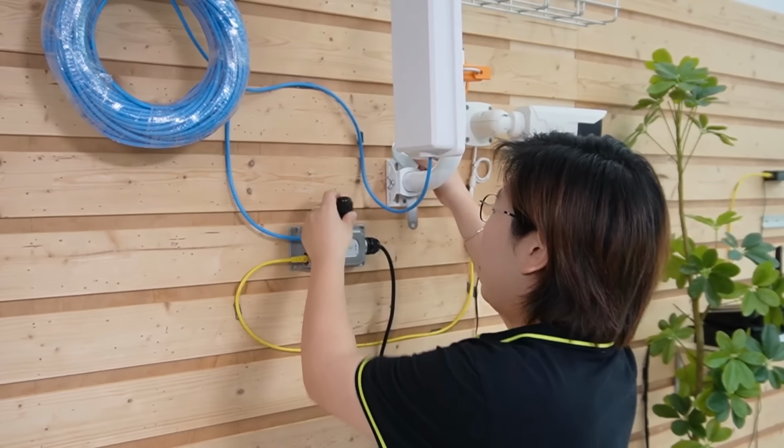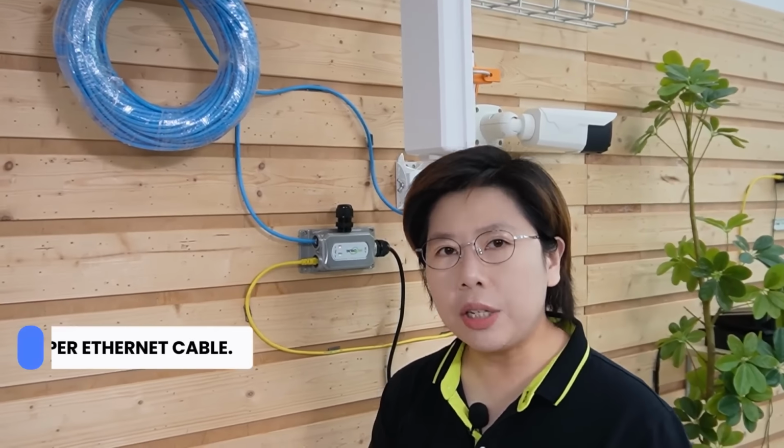And also, don't skimp on the cable. For PoE, especially over long distances, you need pure copper Ethernet cable. Avoid copper clad aluminum. It's cheaper, but it resists electricity and creates heat. In freezing temperatures, CCA can crack, so pure copper is more flexible and conductive.